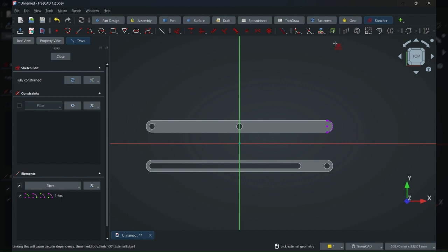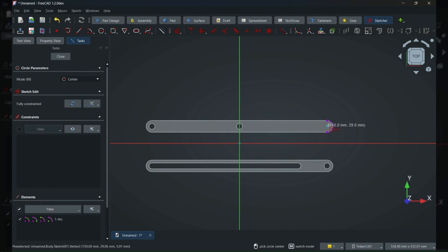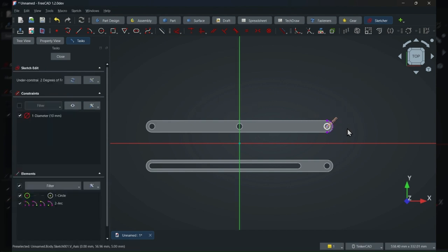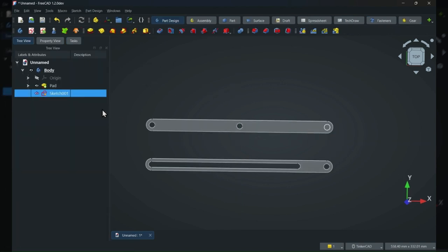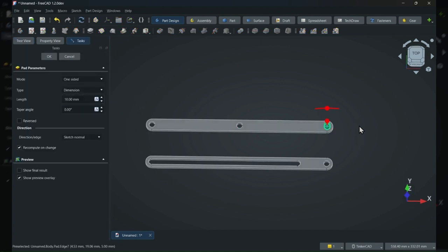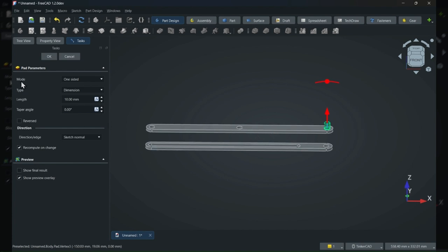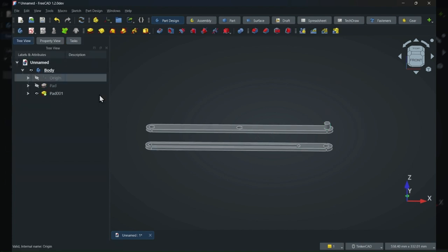So now we have outside geometry in. So now I can line up this hole with my new post. Ooh, that'd be kind of cool. So let's do this. We're going to draw this, and we know that is 10 millimeters. Hit enter. I'm going to close it. So now I've got the drawing on the surface, and I'm going to pad that from there. Look at that. See? So now you've got a 10 millimeter post on there.